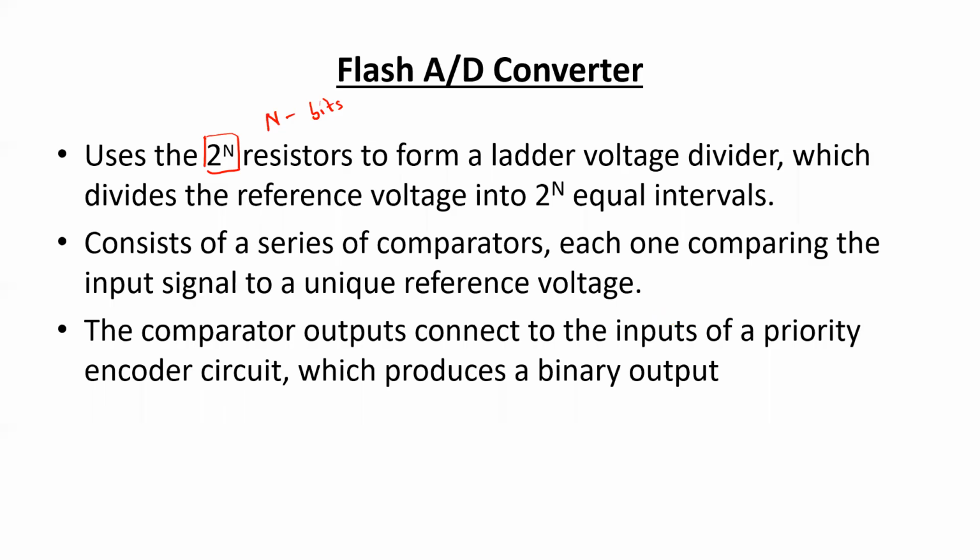Along with these 2 to the power n resistances, the ladder network will generate unique reference voltages which will be used to compare using a comparator circuit.